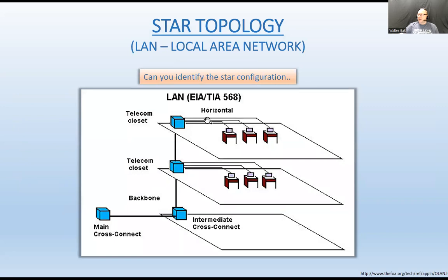These are connected to that communication closet in a star topology, which means every computer, every smart device home runs to the central location. What would be the other way as opposed to home run? Well, it would be one wire there and connected to the first one, connected to the second one, connected to the third one. It would be like daisy chaining things or running things in line.